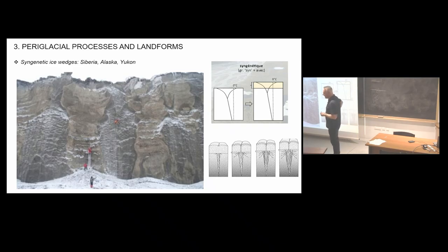Yeah. So you say 70 to 80% of water even in the rock spot? Yeah. Here, this is wind-blown silt. We call it loess. So small particles, 60 to 90 microns, deposited at the surface, and then you have plants that grow. So it's organic matter. And when I said that syngenetic permafrost is super ice rich, that's it. It builds slowly in the soil, and then you have this very high amount of ice there. And it's beside pure ice. So it's almost a huge lake.